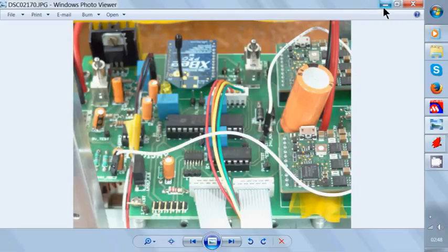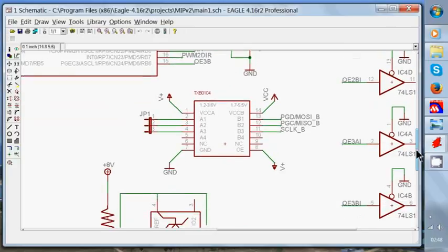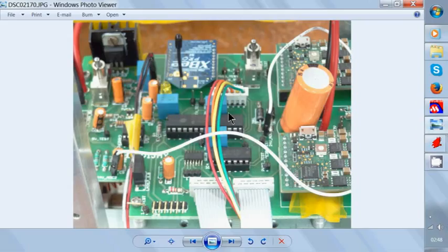If in case an additional board needs to be mounted on MIP in order to do some tasks using vision or for some further advanced processing, this port can be used to access all the states calculated in the PIC microcontroller and do the processing on the secondary board, and then return back the PWM values to the PIC microcontroller in order to be applied to the drivers.